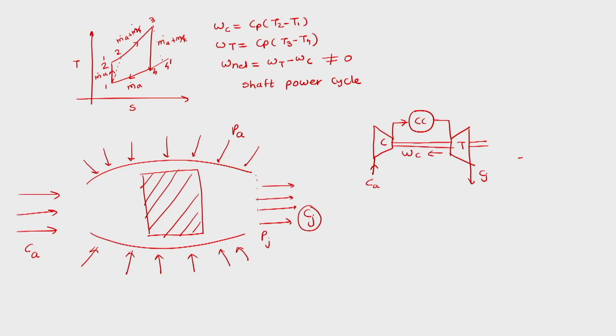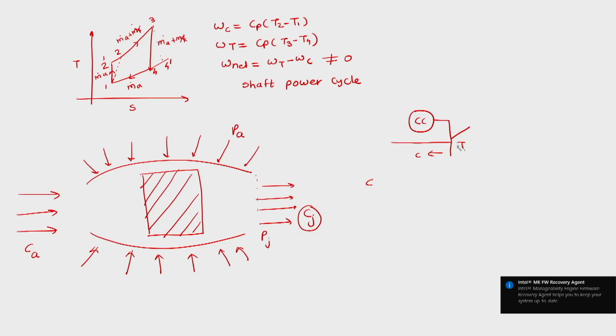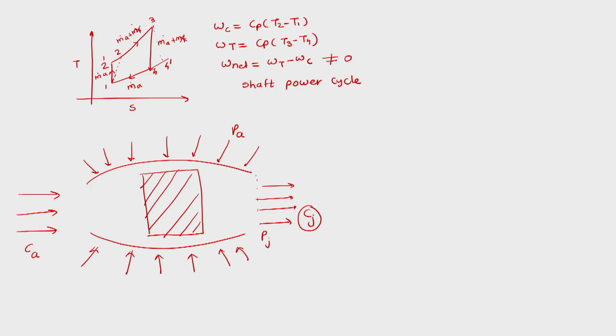So having said this, we need to make a new arrangement or new performance parameter for the transportation application based thermal power plant or Brayton cycle based power plant. In this case, we have many objectives to decide or design a Brayton cycle based gas turbine power plant. So in that case, we might have an objective to work upon maximum thrust, we might have to optimize for economy in case of cruise or steady flight. So these objectives need to be thought through, and these objectives would have certain quantifications, and those quantifications need to be assessed while comparing two Brayton cycle based power plants.